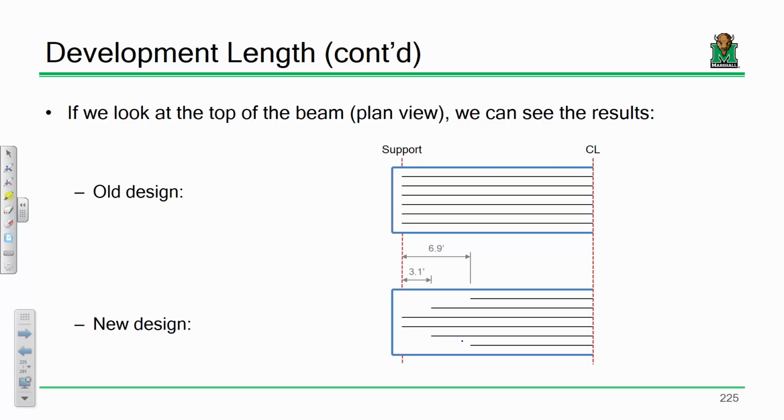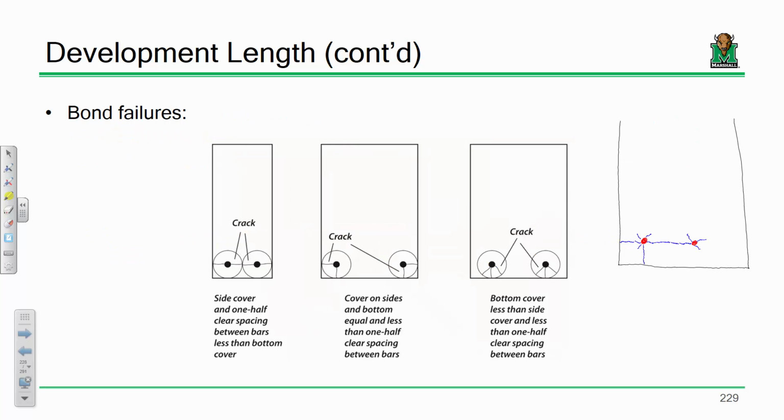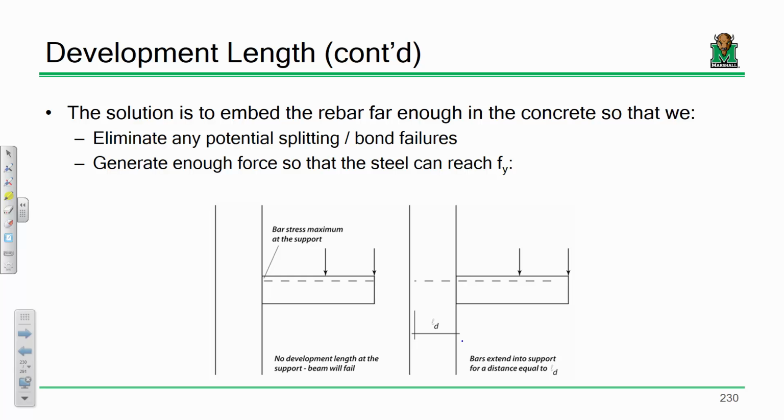Anybody else? This is good stuff. Into the adjacent element, yes. So another really common example is imagine if you're designing a retaining wall. Imagine taking this and sort of sitting it up. Now in geotech you're learning about the earth pressures and the overturning moments on the wall. But one of the things we have to handle is this. We can determine the moments on the wall just using statics. But our job as reinforced concrete designers is how far does this bar need to be embedded, let's say, into the foundation in order to keep that wall upright? Does that make sense?